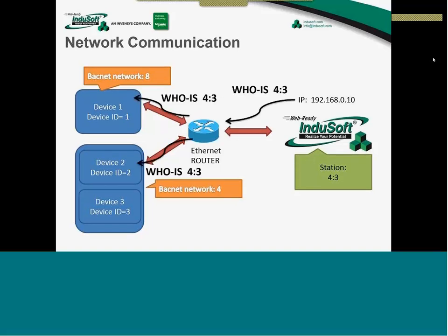And then what will happen when you run the driver? When the first read occurs, the driver will send a Who-Is to the broadcast, asking for device 3, network 4. And you can see that not only this device will receive the message, but all the other devices will receive the message. It's a broadcast message.